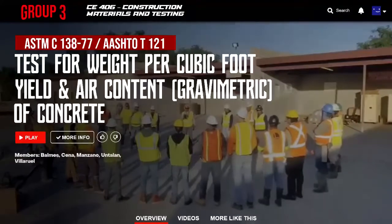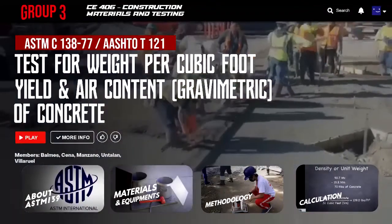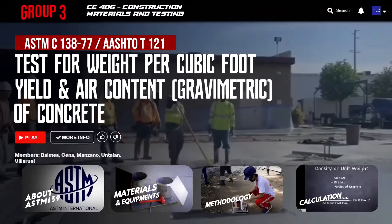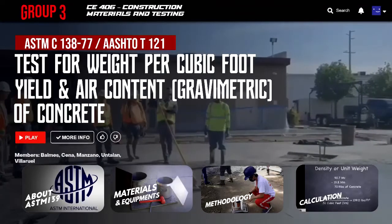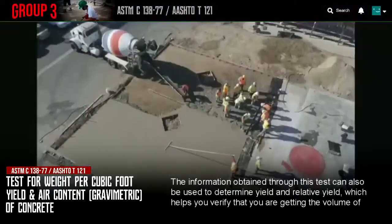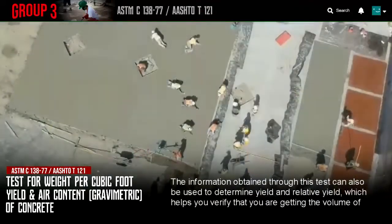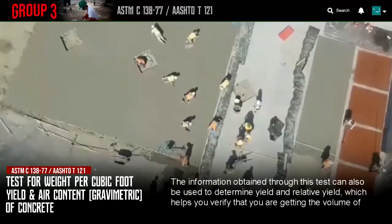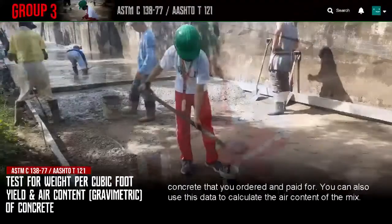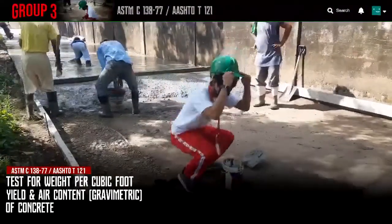This test method covers how to determine the weight per cubic meter of a freshly mixed batch of concrete so that we can get the data needed, like the yield, cement content, and the air content of the concrete. The information obtained through this test can also be used to determine the yield and the relative yield, which helps you verify that you are getting the volume of concrete that you ordered and paid for. You can also use this data to calculate the air content of the mix.